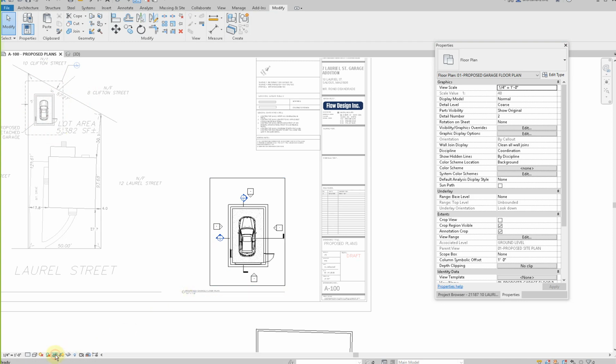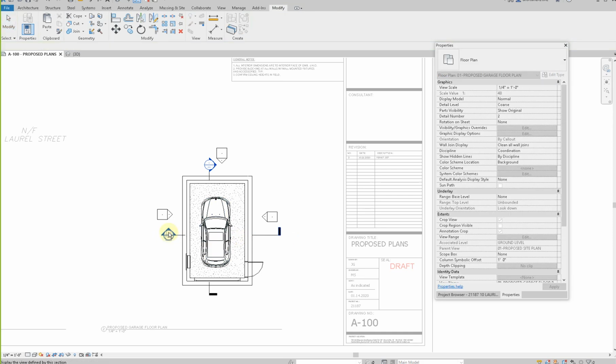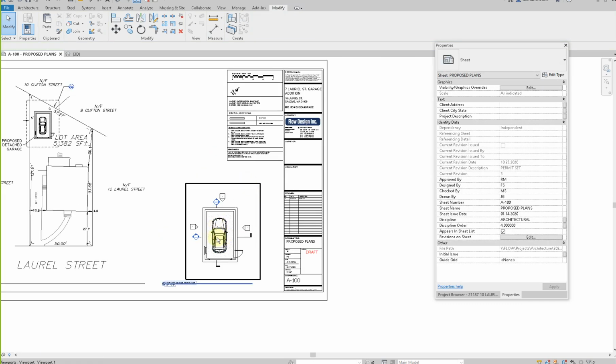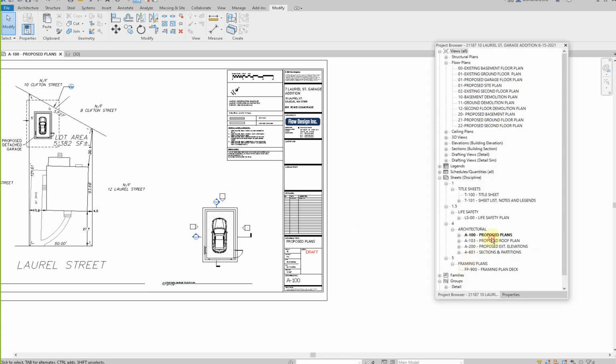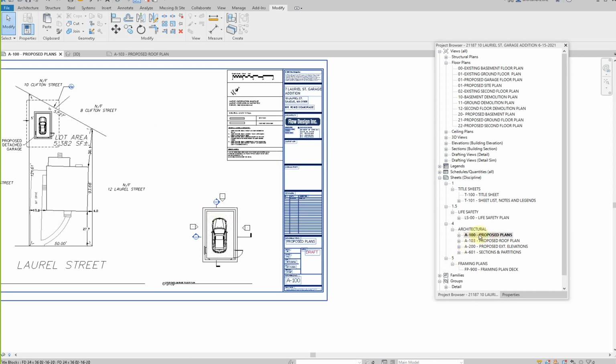So I'm gonna hide the trim, hide that stuff. Move this guy here. And then, I like to see that I'm making progress, which is one of the great things of Revit. I am actually making progress because I could then say, I probably could put the roof plan here too.